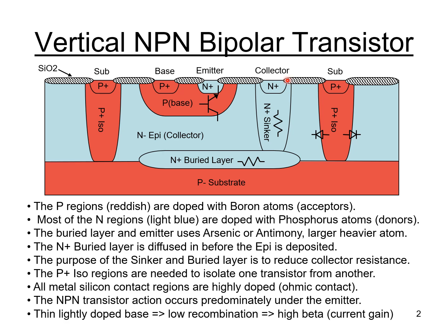So that will give you a more efficient transistor with lower collector resistance. Often you won't see processes with a sinker region. It costs a lot to add an extra diffusion, and a lot of times it's determined that the sinker is not worth the extra money to have it in the process. But some processes have it, so I wanted to show you what a sinker looked like.